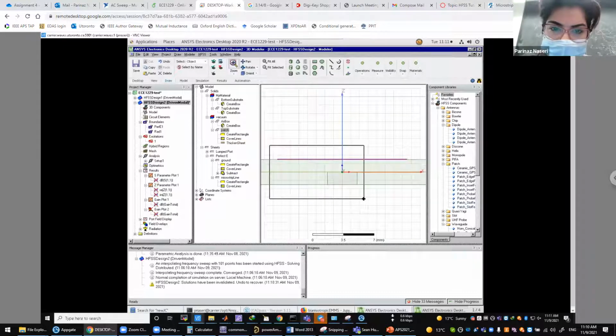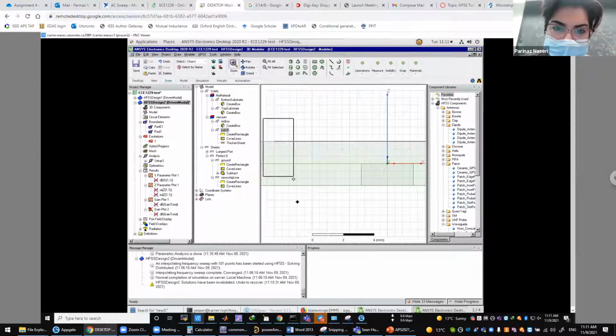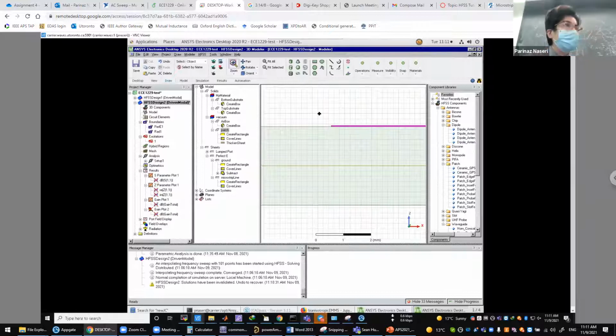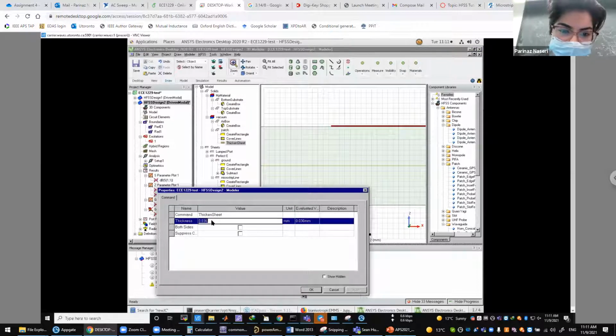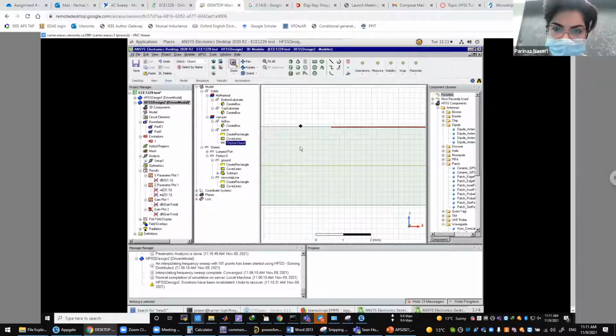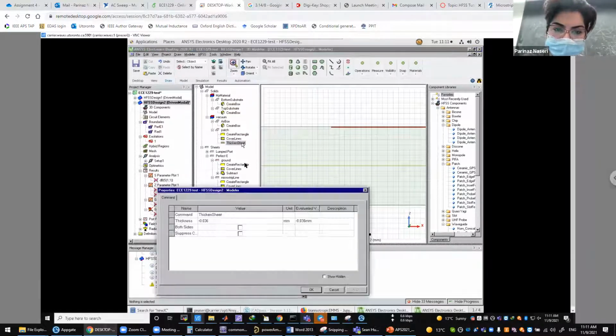So here it did it correctly, you know. The thickness of the metallization has to go up from the dielectric, right? It can never go down. Like as you would put these copper tapes on your plastic or your dielectric, it would go higher than the dielectric. So this is good. But you can even make it minus, and then this would go down. This is not okay, but let's say you wanted to do this.